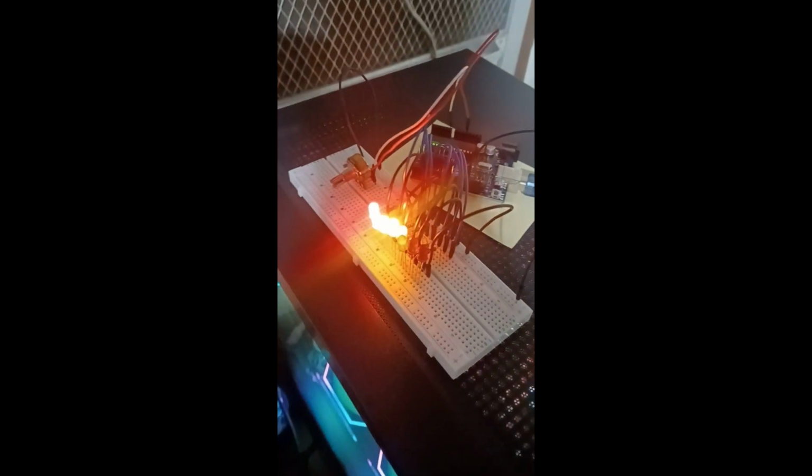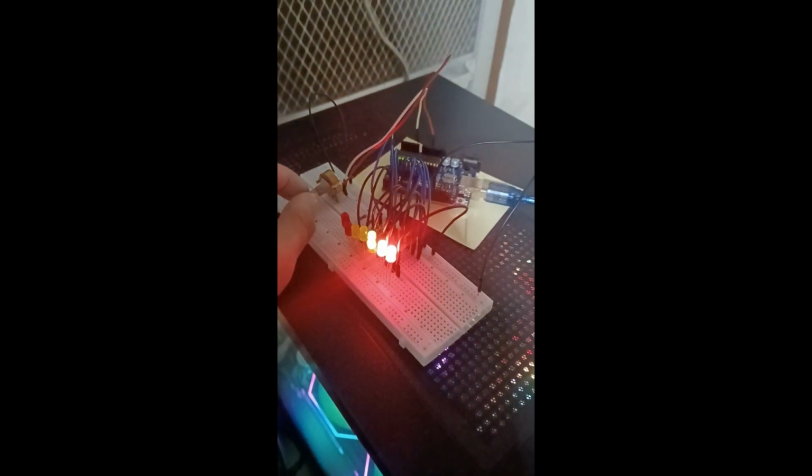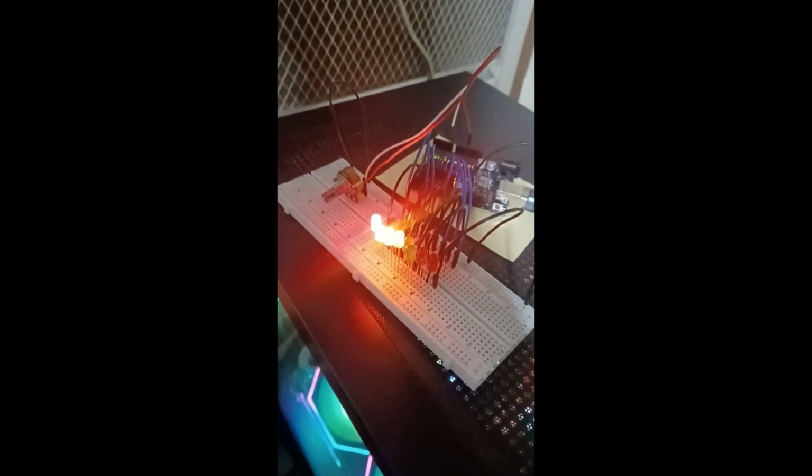So this is the output for the interactive LED flowing lights. As you can see, we have the breadboard here, the Arduino Uno, the LED lights, resistors, potentiometer, and some jumper wires. When I increase the input here for the speed, which is 20 milliseconds, as you can see, the LED lights loop faster. When I gradually decrease the input here in the potentiometer to 500 milliseconds, it also slows down the speed.